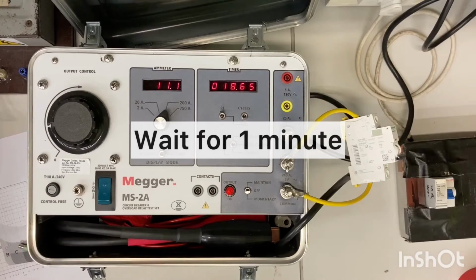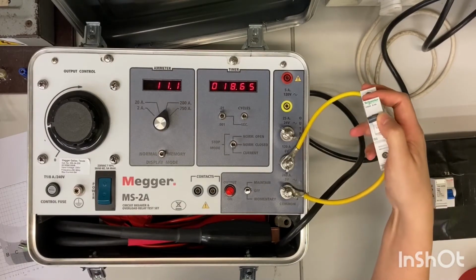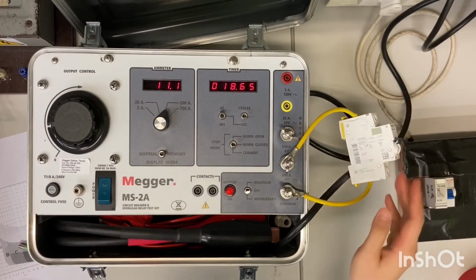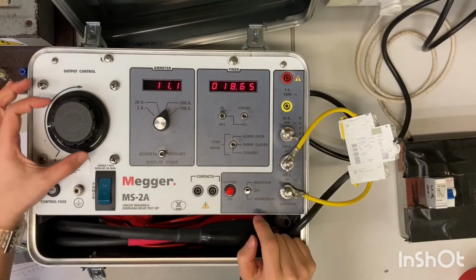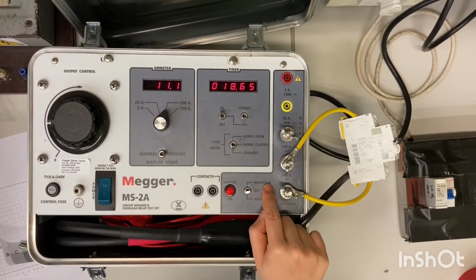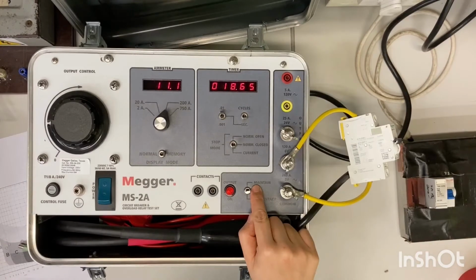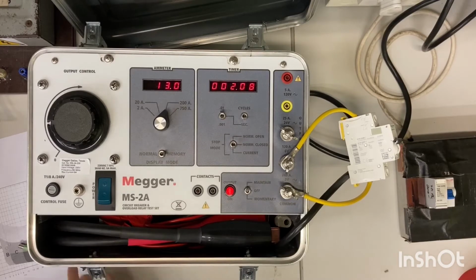And then we need to wait for 1 minute for the circuit breaker to cool down. After 1 minute, we can turn on the MCB and try another current value. The button is still at the off position. Then we can directly turn the knob a little bit to increase the current magnitude. We press the button to the maintain position to start the current injection.